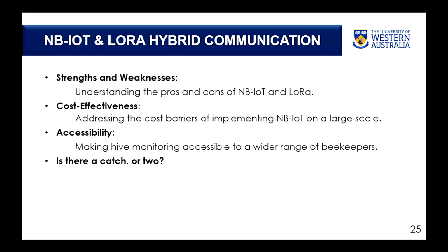So for 9 systems out of 10, I do not need an NB-IoT module. I save power, I save cost. Only one system has to have the NB-IoT module. It collects the data from all the other systems and transmits on its behalf, just like a gateway, like a Wi-Fi router at your home.